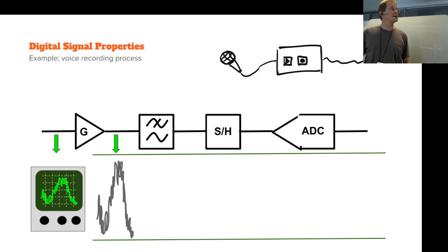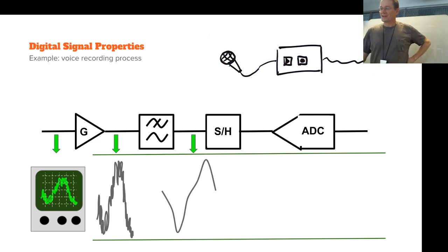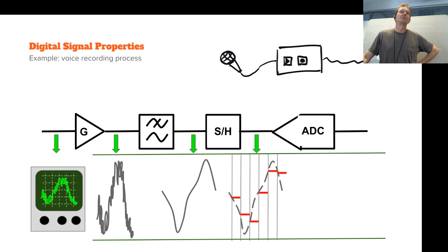Then it has this high frequency noise there. That's why you need to have analog low pass filter. So even if it's a digital system, you need some analog filtering because of aliasing effect. Have you heard of that one? Probably. Yeah, you have been awake on the electronics classes. So preventing the aliasing, you need a low pass filter, and then you'd have the sample hold.